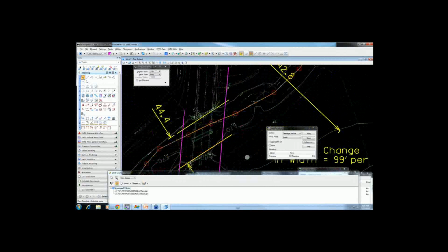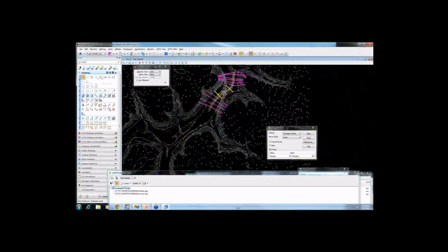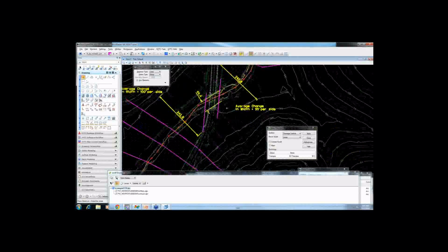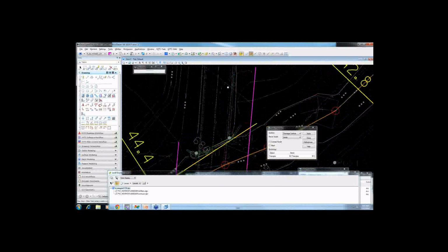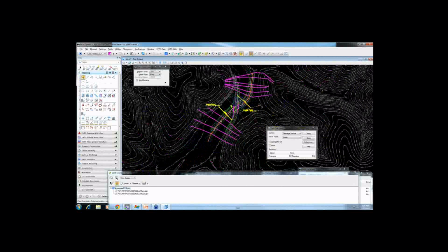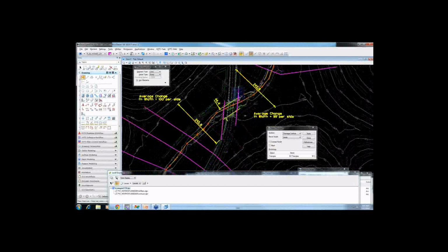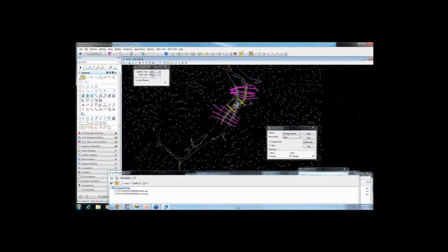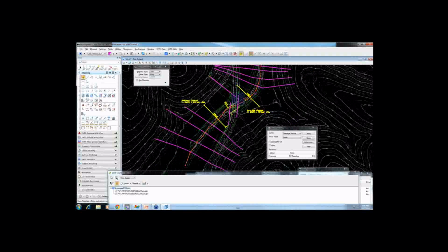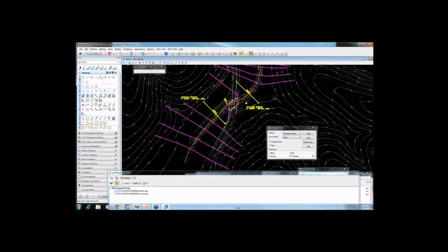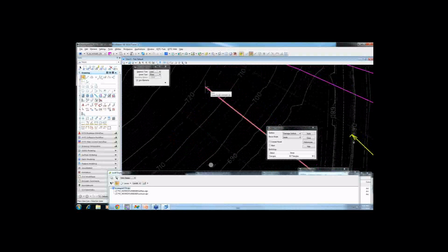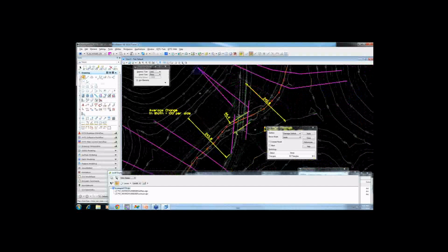And since it's hard to hit like right at this point, if you start out here, I like to just start right here. And what you're looking for is, from a broader perspective from the floodplain, which direction is this water going to flow. So this part of the bridge section is prescribed to be parallel to the bridge, but outside of the bridge it should turn and go with the floodplain. So that generally goes up here. And so that's what I would do, and then I'll come back and just retrace that here.